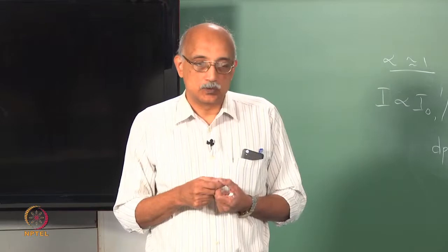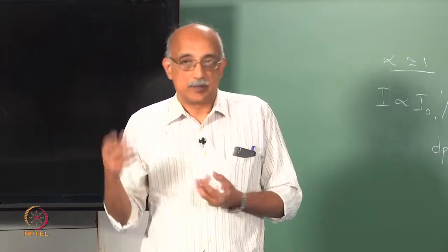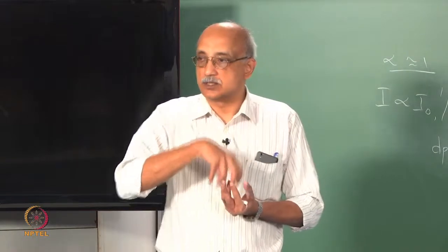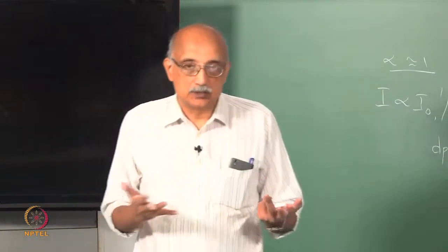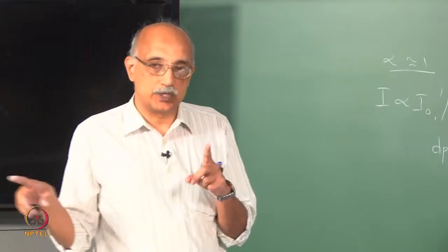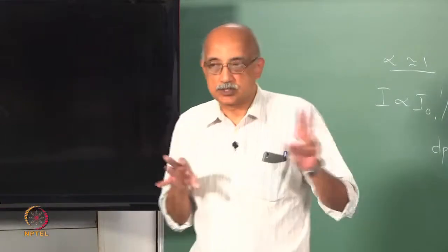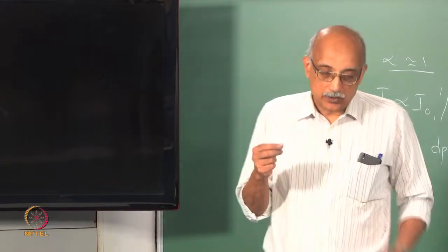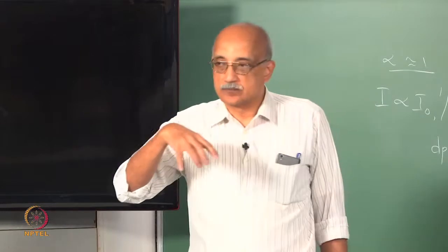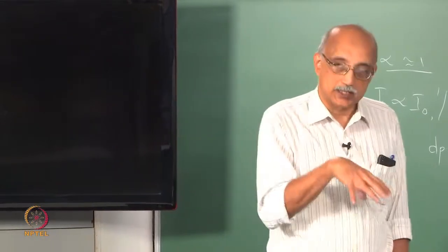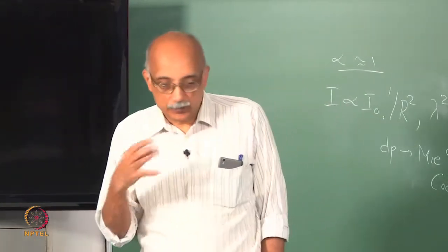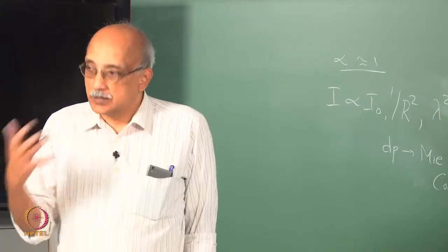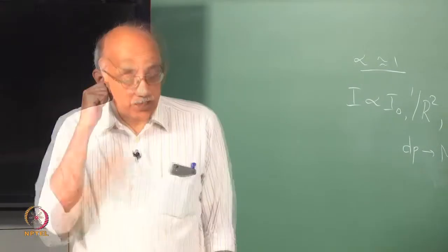And then you correlate the measured sizes to the sizes that would have existed before you started condensing the vapor. So, you have to do some calibration initially to understand the relationship between the measured size versus the actual size, but once you have done that exercise once, provided you can control the process of this condensation precisely, you can always take particles that are sub Rayleigh regime, grow them to the Rayleigh regime, and then use light scattering as a way to measure particle size.